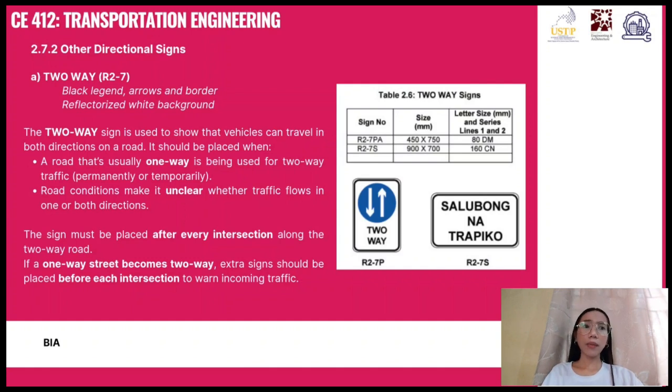These signs must be placed after every intersection along that two-way road. If a one-way street becomes two-way, an extra sign should be placed before each intersection to warn incoming traffic, for advance awareness of drivers.